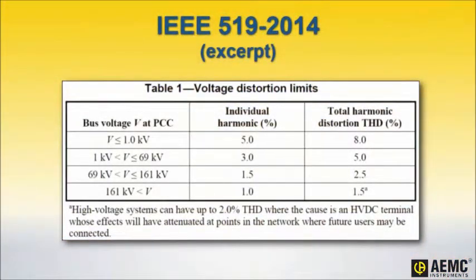THD can also raise regulatory considerations. A number of guidelines exist, such as IEEE 519/2014, that define how much harmonic distortion is allowed for certain types of facilities. Strict adherence to these specifications can be an essential business requirement for many organizations.